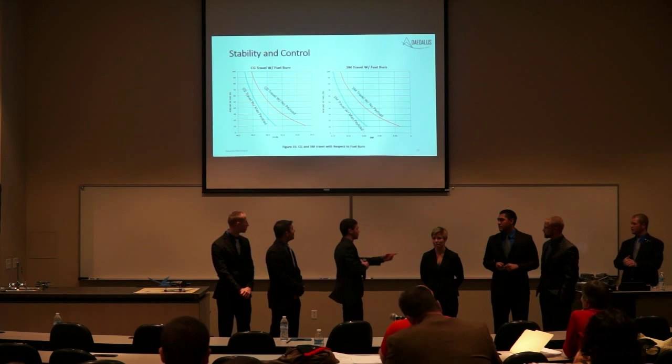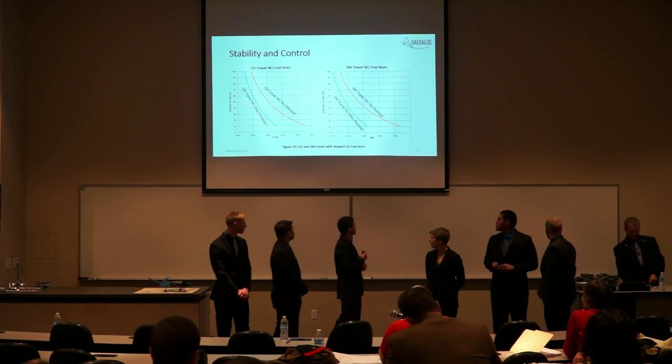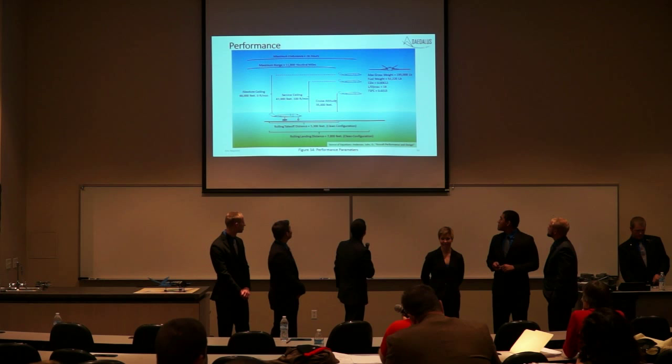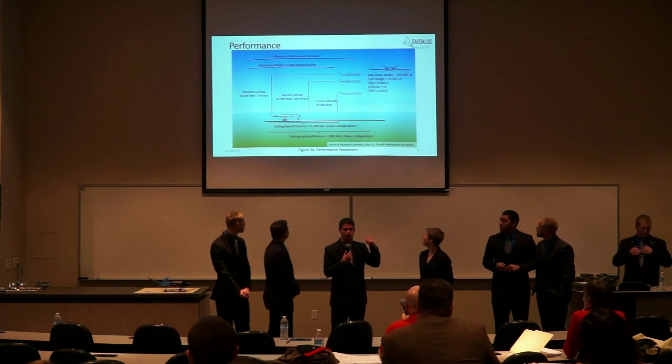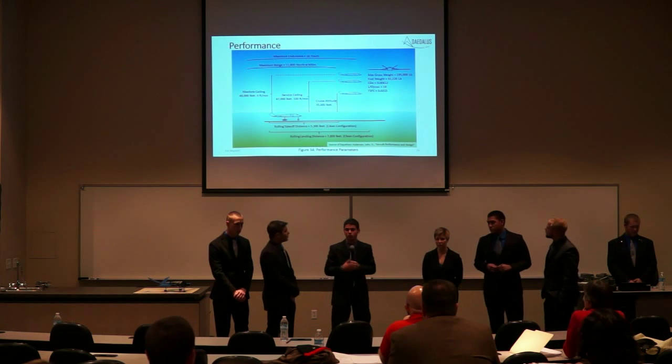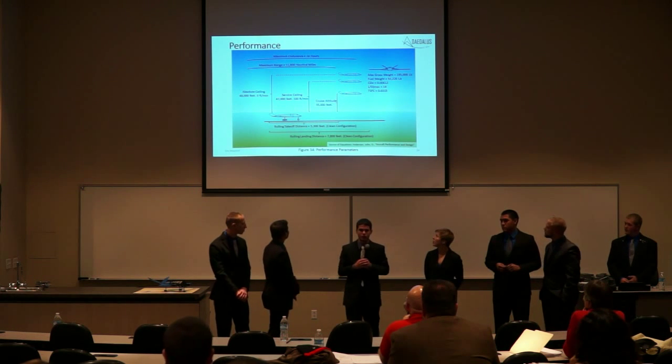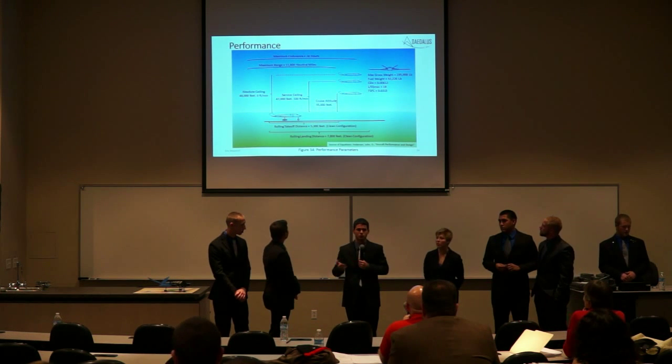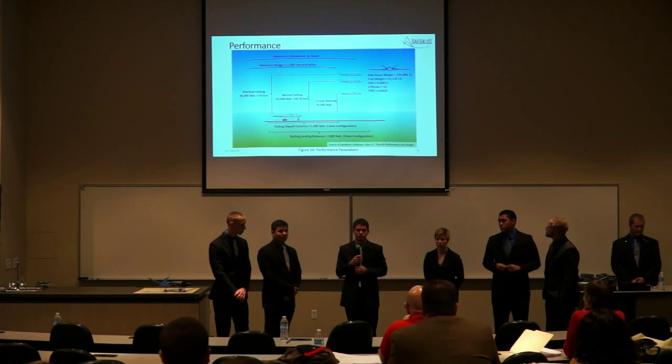Can you go to slide 34? We did do that. Here, these takeoff and landing distances are both with clean configurations. So yeah, it's a big number to have 7,800 feet, but with the deployment of flaps, that would probably come down like 1,000 feet or so.